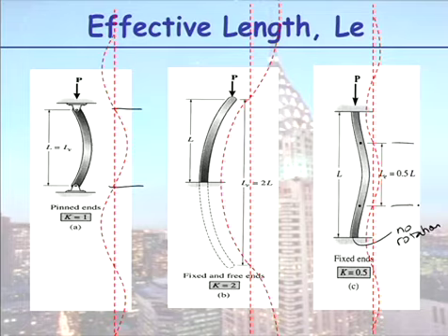And the other extreme case is when you have what I call a flagpole. When you have something that's tied in at the bottom and free on the top, think of that middle case as you have a parachutist that is about to land on top of a flagpole. So he lands on the flagpole and the whole thing will just bow sideways. So where's your half sine curve? It's actually double the true length. So your effective length is now 2 times the true length.